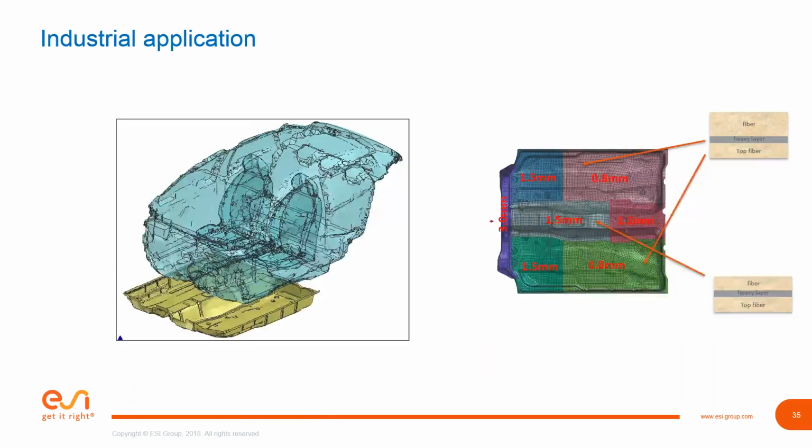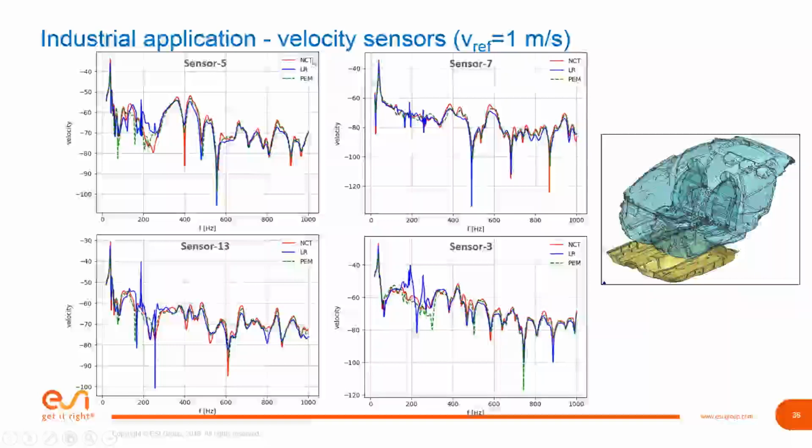So we have a case study, a validation example with a carpet, different sections, different layers, different trim configurations. The red curve is that new noise control treatment, the non-locally reacting. The blue one is the locally reacting, the 2x2, and the dash green is poroelastic material. You see, with a couple small exceptions, most at low frequency, very similar response. In this particular case, this built some confidence.